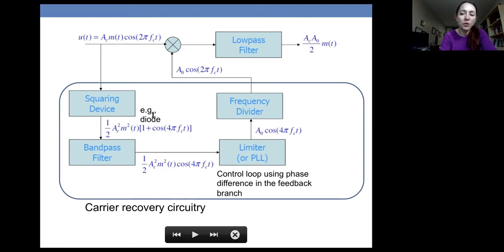Once you get a nonlinear electronic circuit that produces second order components, you can then use it as a squaring device. What would you do? You would only use a second order component through appropriate filtering. But for now, suppose the squaring device is exactly doing the squaring, eliminating all the other higher order terms, eliminating any DC term, etc.